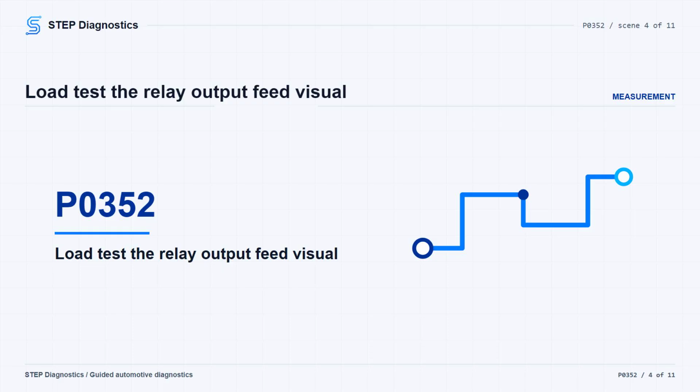If you voltage drop it, compare the voltage across the bulb to battery voltage, and compare bulb brightness to a direct battery connection. As an example, 2.0 ohms of resistance in the circuit being tested can make the voltage across the bulb 25% less than battery voltage because the total circuit resistance becomes 8.0 ohms. If the bulb is not bright, repair the 12-volt circuit for an open or high resistance. If the fuse is open, check that circuit for a short to ground. Then verify the repair and confirm the code stays gone.